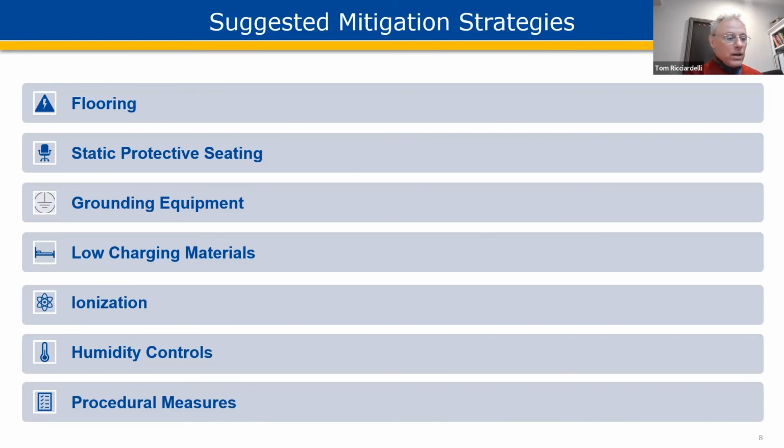There are other things you can do. For example, when you have tablets where you may be collecting data out in the facility, and bring them back and dock them, there are things you can do in terms of grounding those properly before you attach to the docking station to help mitigate the opportunity of a discharge happening through the device and causing data corruption. So every device is going to be different. Again, this is going to be very case specific, but there are things you can do to just kind of control the environment and control the risks that might happen. So those are the basic things that you can do in a healthcare facility. They're the things that will be discussed in this document, and they can be very effective.